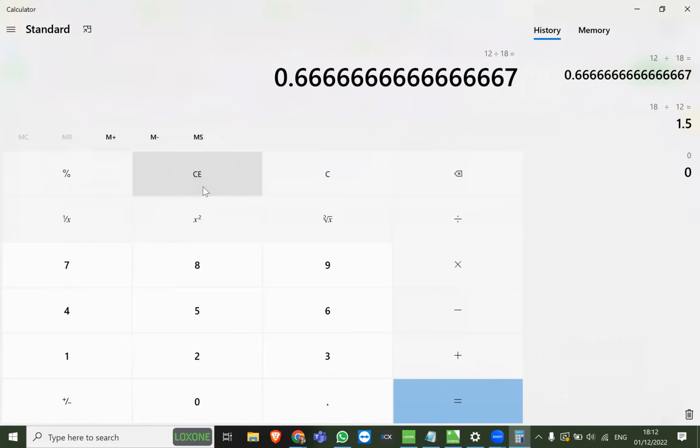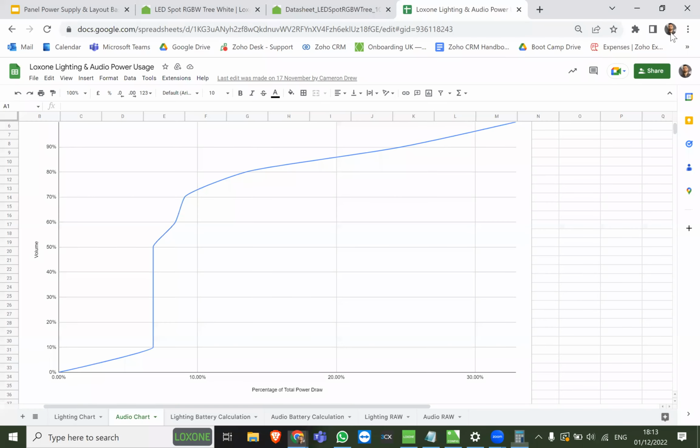So we're only using about 66% of the maximum RMS that's on the datasheet at full power. And even if we go with the datasheet with 18 watts and we spec it out this way, we still have a lot of headroom when it comes to how much power, or how much music we can play through a speaker, or what volumes we can reach.